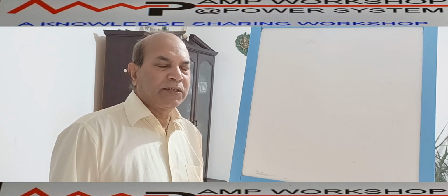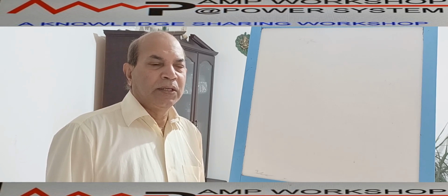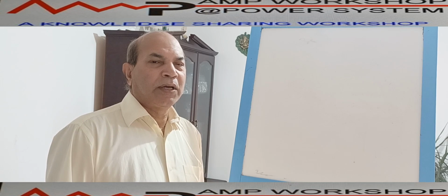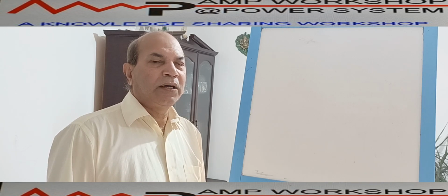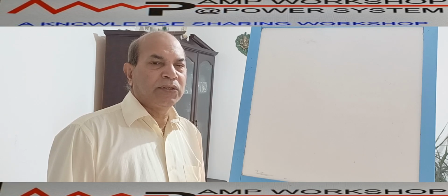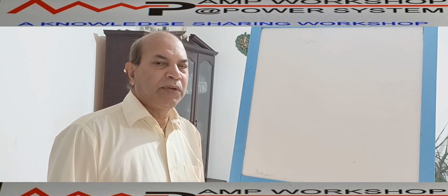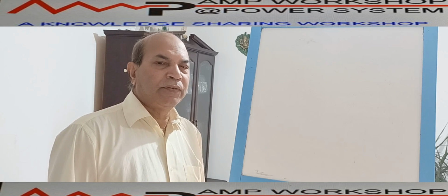procedures. First, in video number 58, we have discussed the basic symmetrical components resolution to calculate the asymmetrical fault current, and in the second video we have shown how the various load impedance can be decomposed into positive, negative and zero sequence impedance. Using those, we have also said that this positive, negative and zero sequence component of impedance is the basic module for the calculation of asymmetrical short circuit current.